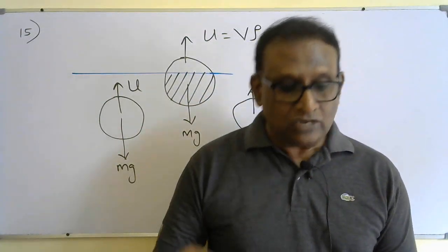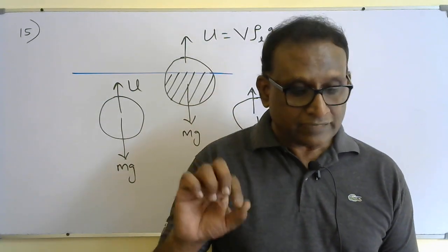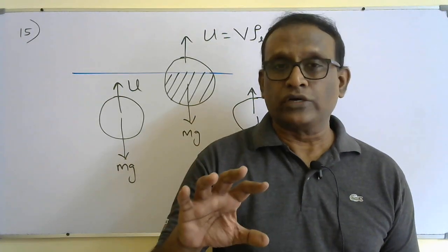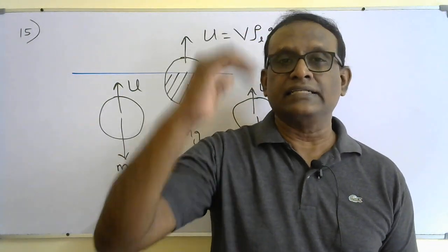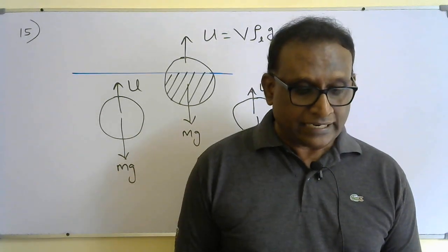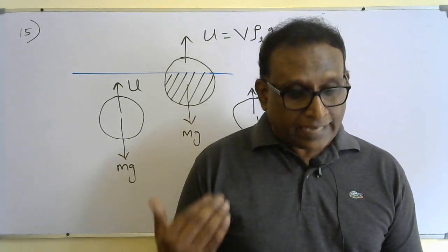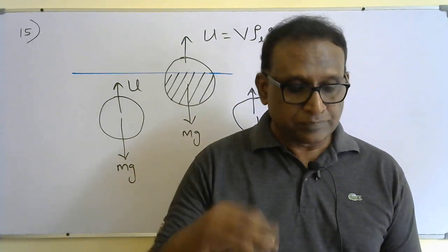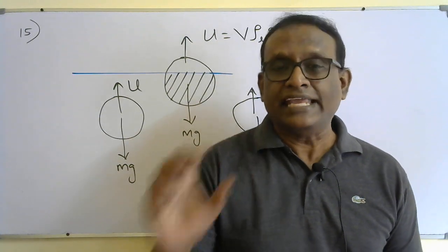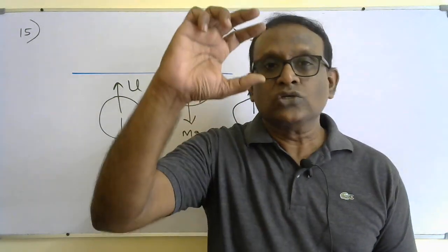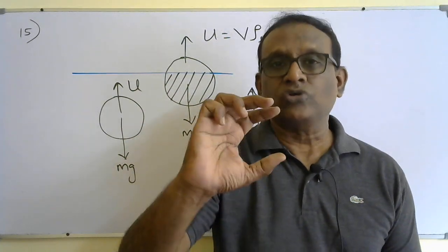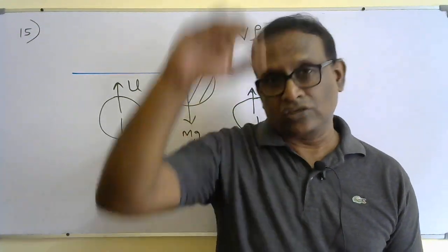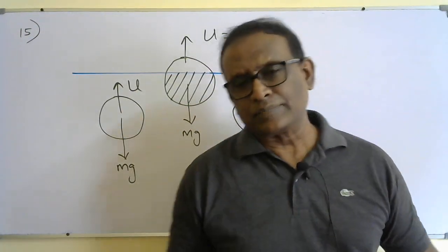But the total weight of the bulb and the disc marked with 26 degrees Celsius is lower. So still it is floating partially outside the liquid level. But when the temperature becomes 26 degrees Celsius, what happens? The total weight of the bulb and the disc marked with 26 degrees Celsius will become equal to upthrust. So it will go slightly further down and float. But if it becomes more than 26 degrees Celsius, upthrust will become smaller than total weight, so that also will move down. That's the principle they are using.